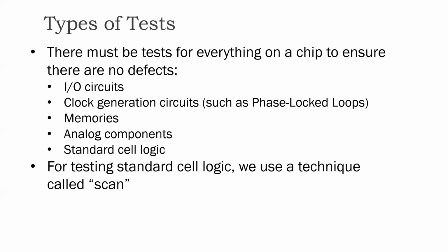There are other kinds of tests you have to do for I/O circuits, memories, and so on. We are not going to cover that in this class. Those kinds of things will be covered in a class on design for testing or DFT. I just want to cover scan because we are focused in this class on how to implement logic circuits involving standard cells, and inevitably any standard cell based logic circuit will have the scan logic built in, in order to enable the testing of that standard cell logic. So it's important to understand scan and how it impacts the design.